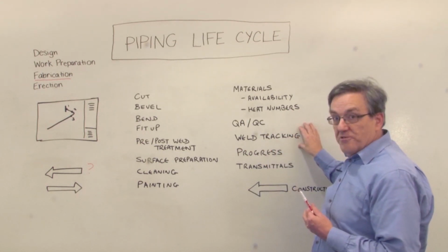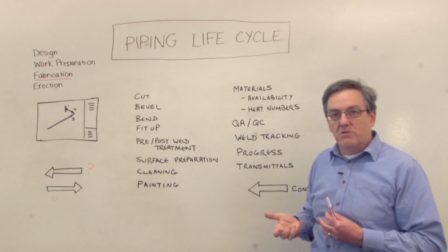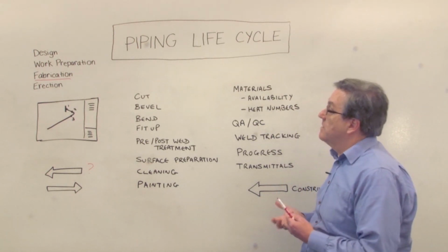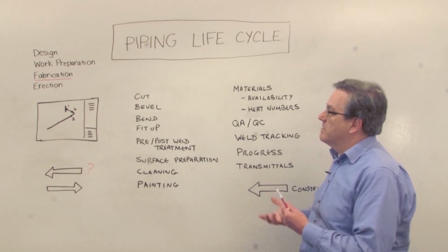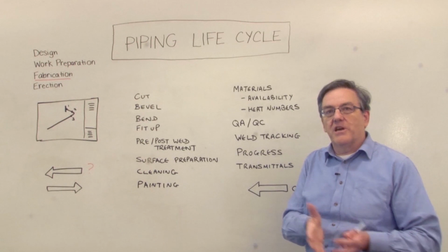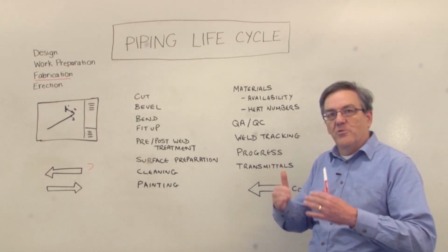We probably want to track information about each weld: when the weld was made, who made it, what qualifications they had at the time, the result of the test. So we can see across the project and across the company the standard of performance that we're meeting.